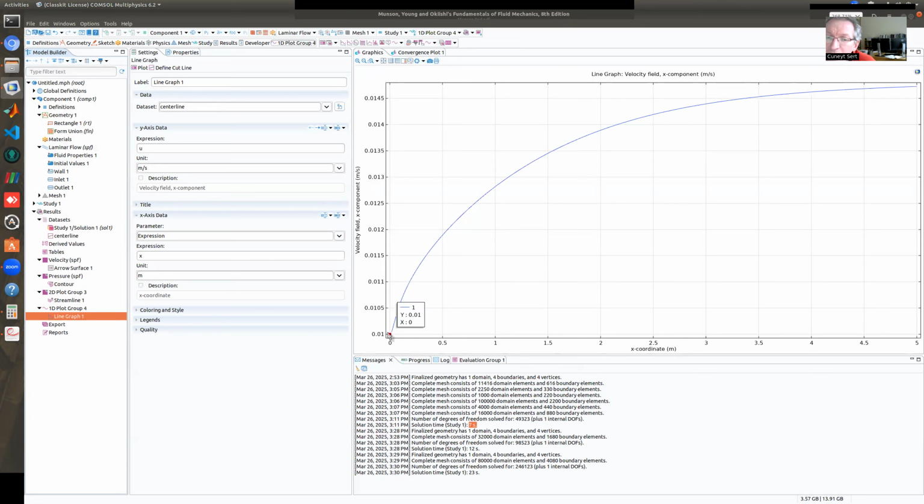It starts from the inlet condition and then speeds up and speeds up and speeds up, and then it just kind of not changing anymore. And we are almost at 0.015. If I make the channel slightly longer, a bit longer, I think fully developed condition can be seen.